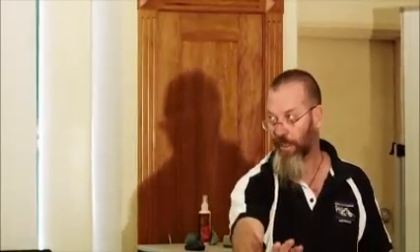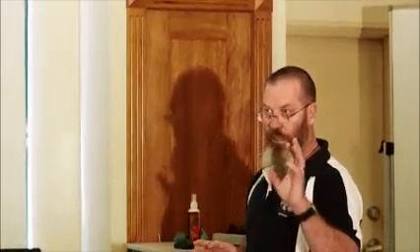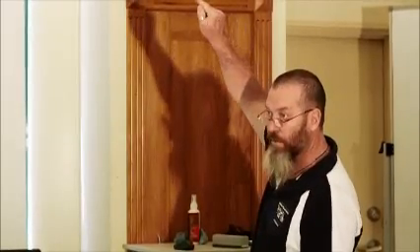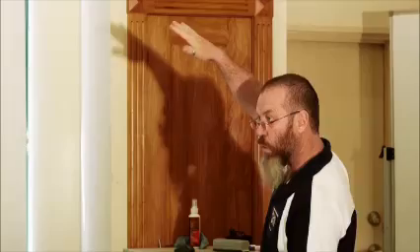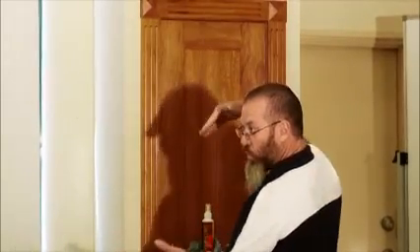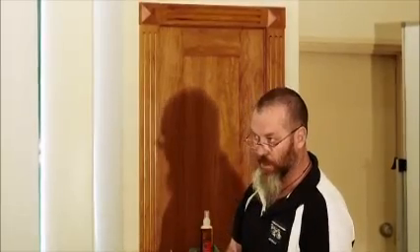Or if it was a single story building where you've got your bottom plate connected to the slab, again you get it from that third row. So in a single story building, you'd actually be using 3 rows out of the table. You'd be using row 1 for your batten connections, row 2 for all your roof frame connections and all your wall frame connections right down to your stud bottom plate connection, and row 3 where your bottom plate was connected to the slab, if it were a slab.